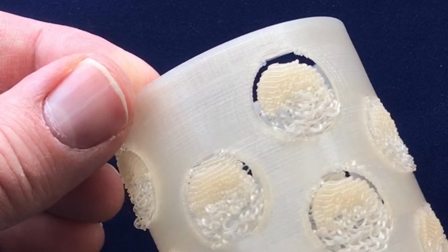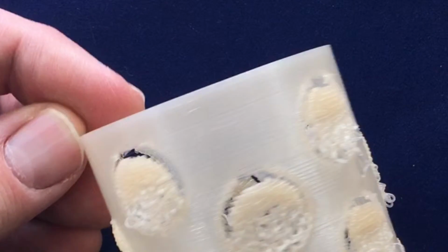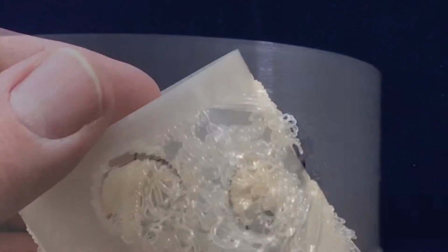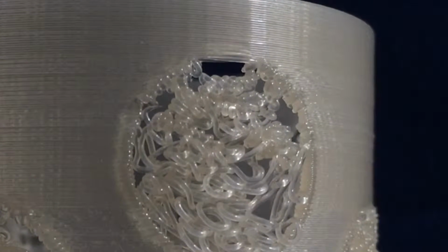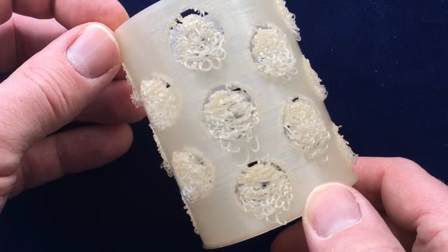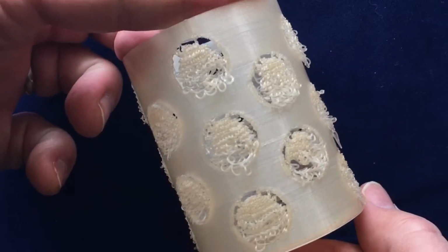This is what it looks like when drop Z scale is set to 1. There's nothing connecting the top of the drop print part to the rest of the vase, whereas here I've got the drop Z set to like 1.2 or something, and that way the top of the drop print part is attached to the vase and it holds inside the hole better.